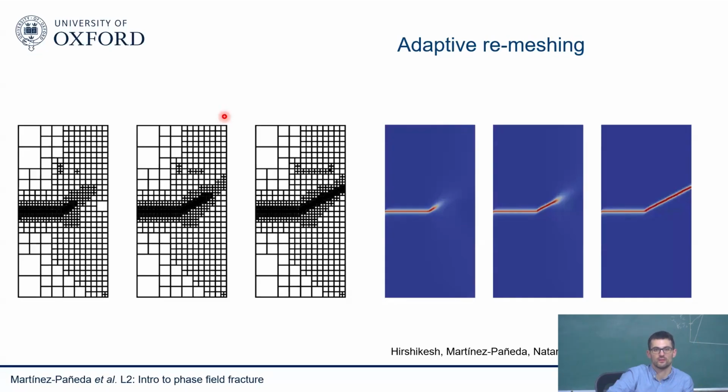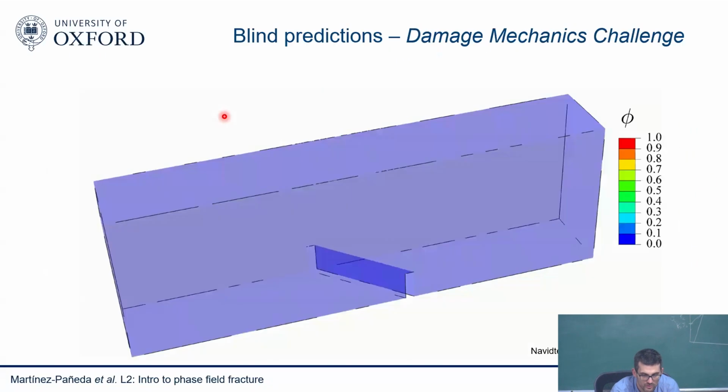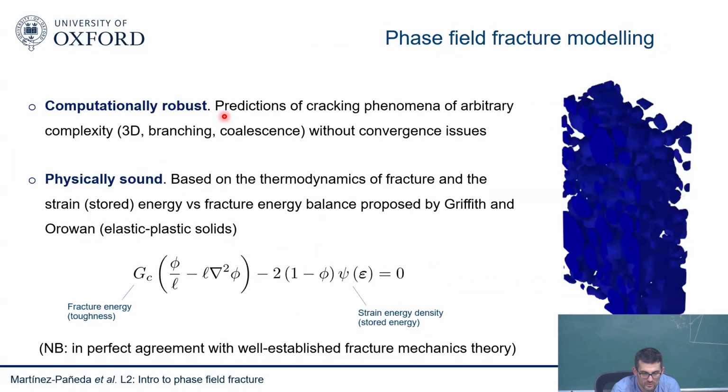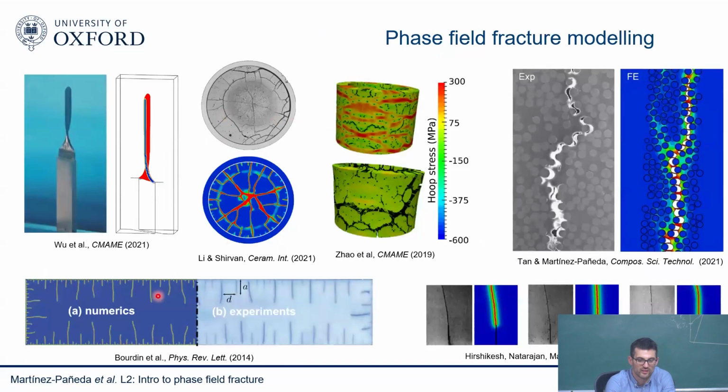Yes. So there's nothing, that's the beauty of it. You don't have to do anything. You're solving for the phase field. If it's energetically convenient for a crack to nucleate or branch, let me take some of the examples. This one was from, you can see here. If it's energetically convenient for a crack to branch or nucleate a secondary crack, look at this one, quite remarkable, this thermomechanical experiment. This is thermal shock, so you have something that is at a high temperature, you put it into a bath at room temperature, and then cracks initiate, and the spacing is related to the change in thermal load and so on. And you can see that the experiments and the model agree quite well.